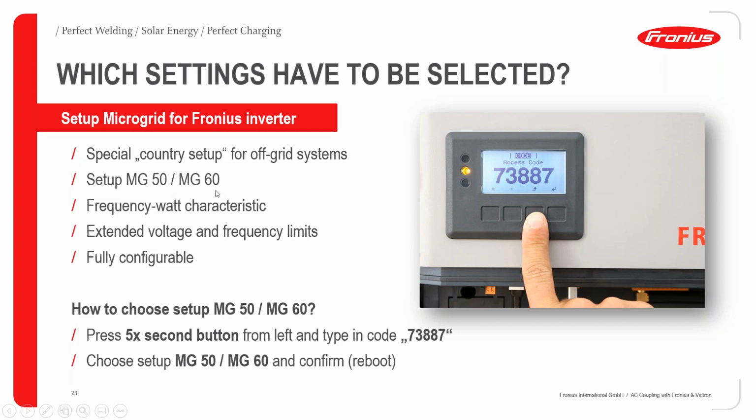The 50 and 60 represent the operational frequency of the region that the system is being installed in. If it is 50 Hz, then you use MG50. If it is 60 Hz, then you use MG60. This ensures that we have a seamless line of communication. And there is also a possibility of extended voltage and frequency limits to ensure that the system communicates seamlessly. This is fully configurable.